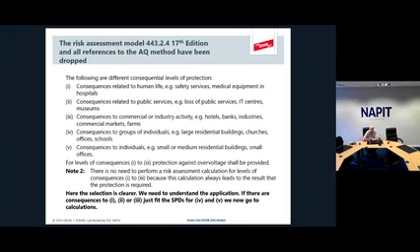We look here at the consequences. So if there's a consequence to human life, public service or commercial activity, they give some examples, and it says there you don't have to do any risk assessment, you shall fit the SPD. Well, there's a little bit of wordplay going on out there. So it says there on indent 2, but if it's say an IT centre, you'd fit SPDs. Well, I'd go to a site and they say, yeah, well, we're not going to fit them. Oh, why is that? Well, it's not an IT centre, is it? It's a data centre. That's not on the list. So this had to be firmed up a bit and get rid of any ambiguities.